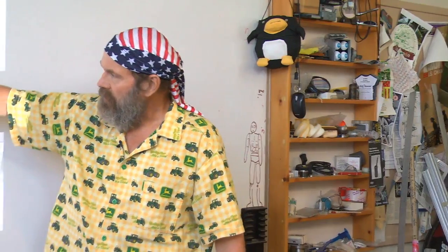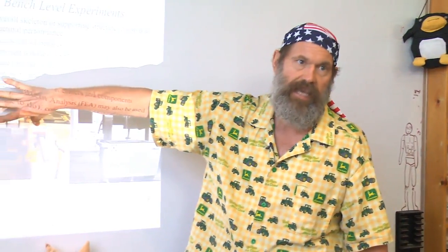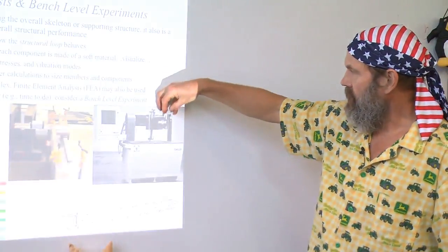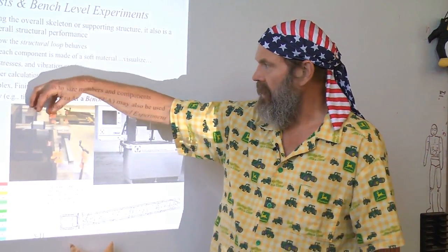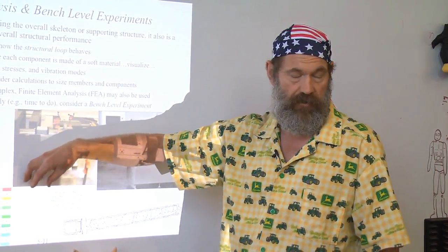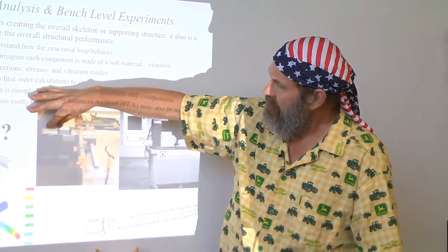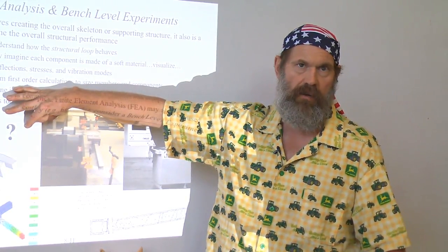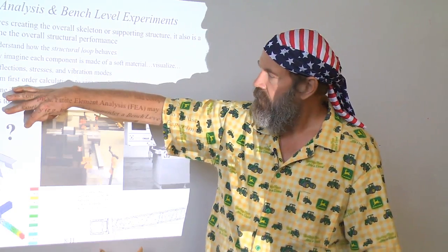As we went up in size, things didn't work so well. Why? Because remember we talked about earlier, the stiffness is a function of the length cubed. And one of the functional requirements is to hold the container of sand on the structure. That's the abrasive that's used in the water jet. And as this started to get a little bit longer, marketing said, well, we think we want this, quote, small machine to have a slightly bigger cousin.